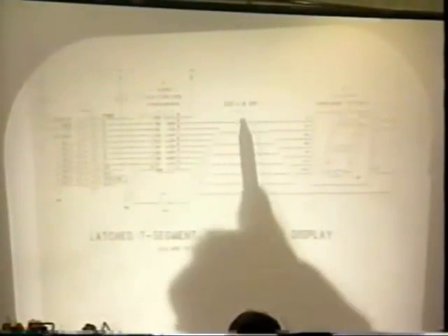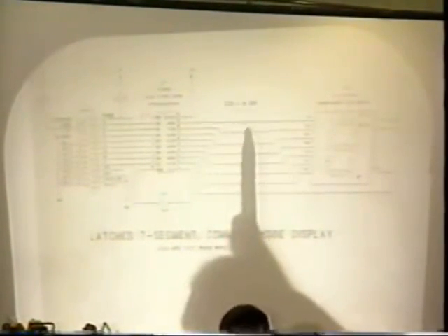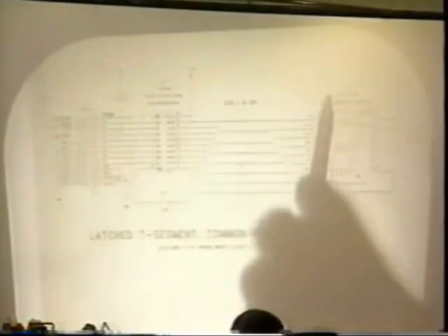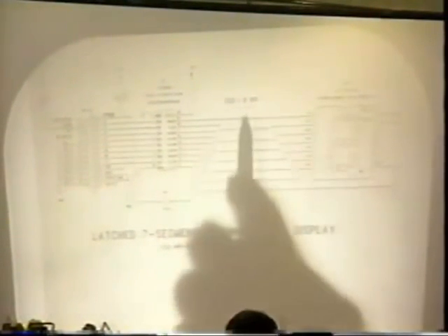And then there's a resistor in series with that, and the reason we have a resistor is so we don't put too much electricity through here and burn out my LED. The LED will burn before the TTL circuit will burn. So that's to limit and protect the LED. Very sensitive. Okay, what else can we run?